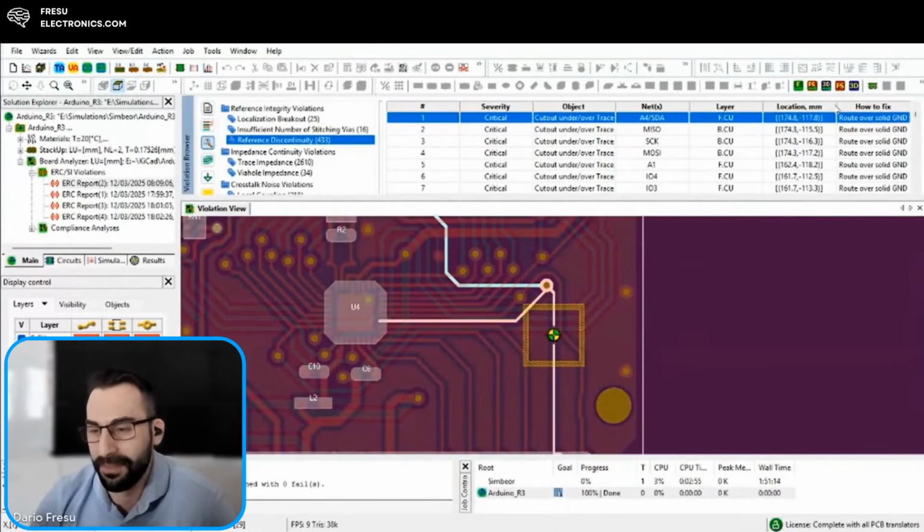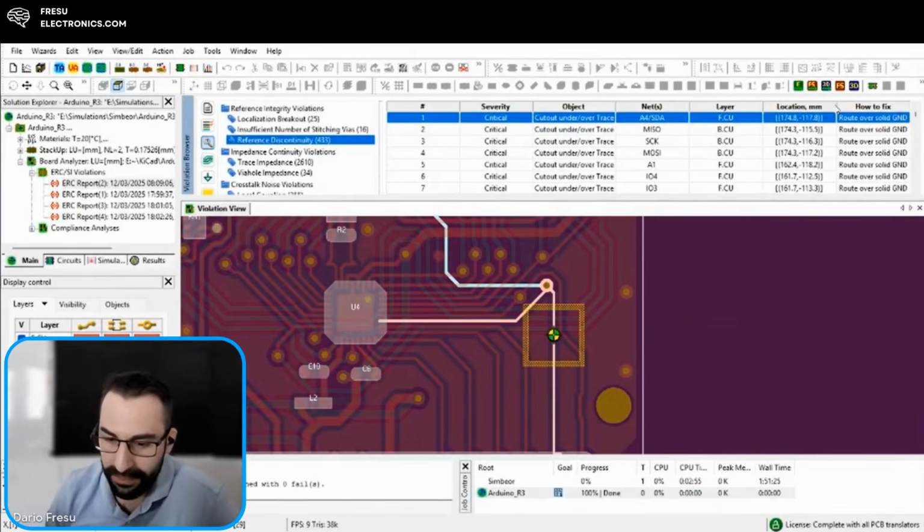When the project manager asks you, how many layers do you need to use for this project in here? You're going to say 2 layers, or at least if it was fairly inexpensive, you would say, I would choose even 3 layers. The problem with choosing 3 layers is manufacturing, because they said, if you want, maybe we can do you 3 layers, but it's going to be quite expensive for you because we don't usually do that. We usually do it in pairs. So which stackup can I choose, which is the cheapest possible, but also the most effective?